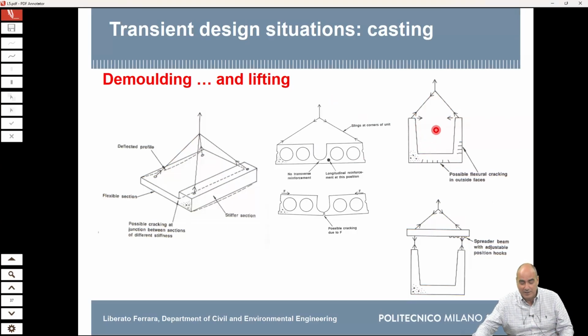The water will be here, but here there will be ground, and the moisture from the ground, generally with sulfates in the soil, which are the most common aggressive agent, can cause early problems of durability. You have designed it for a certain service life, but after 5 years you will start seeing everything leaking through this channel. So these are important aspects where you require careful structural design.